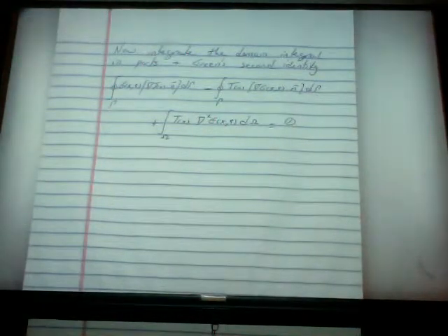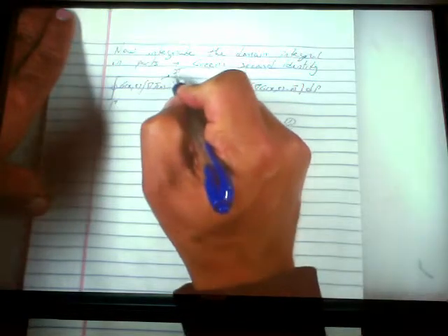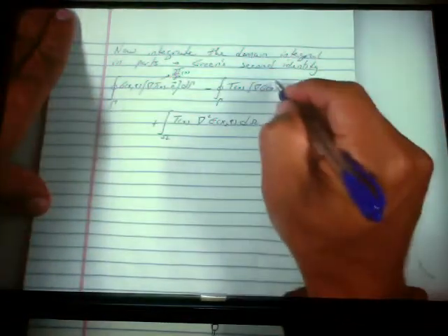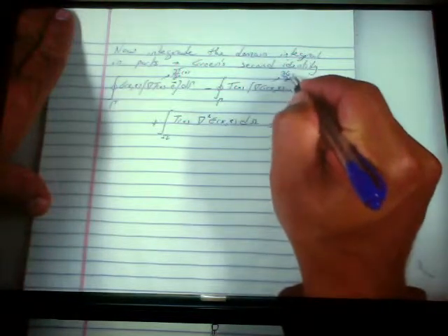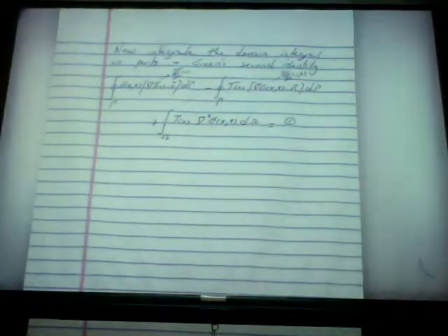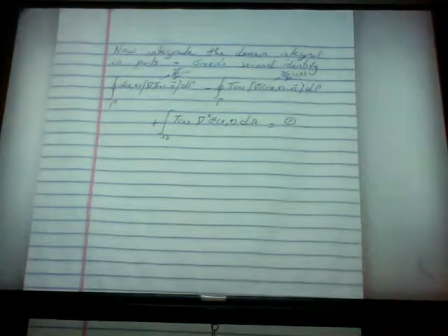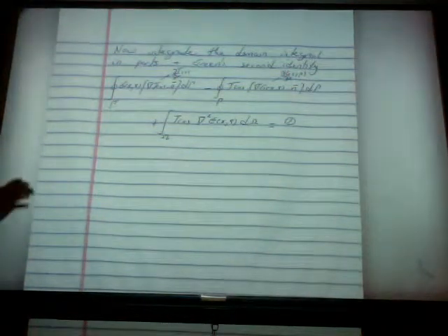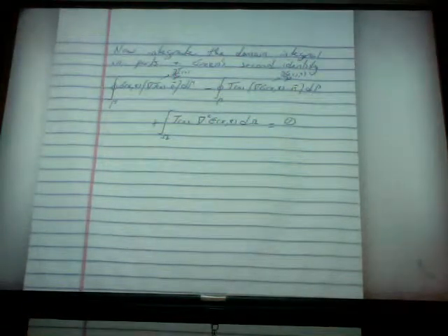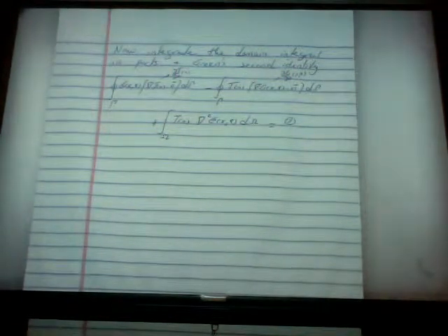All right? Oh, by the way, these terms in brackets: this one is just the dT/dn, and this one is just the dG/dn. Remember that the n is just a normal derivative. So for simplicity, we're just going to say that that's dT/dn and that's the dG/dn. All right. Now, what do we do? Remember that g, we don't know what it is yet. It's a weight function, but we haven't chosen the weight function. Now we're going to pick the weight function.